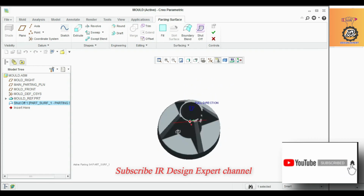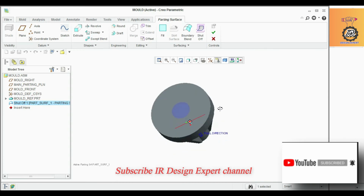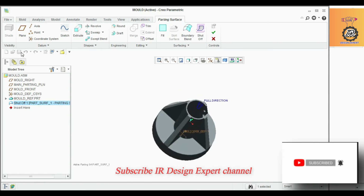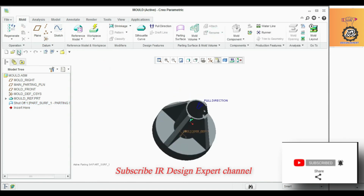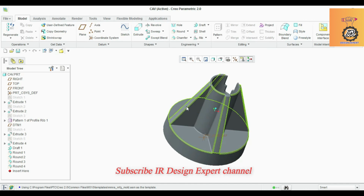Then now we are going to create a parting surface. Before that we can save now. Okay, save the component. Go to the previous component, just click there, window and cavity model. Here you can select each and every component and then copy paste, then only the surface model is created.